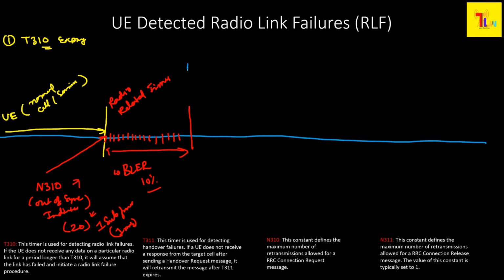At this point your timer T310 will start. If we talk about the values of T310, it is system to system. I have seen the maximum it is 2000 ms or 2200 ms. Okay, it depends on the system.